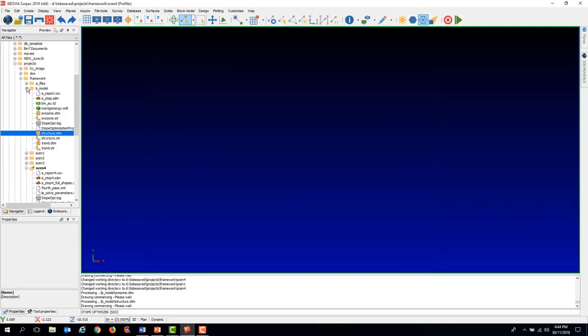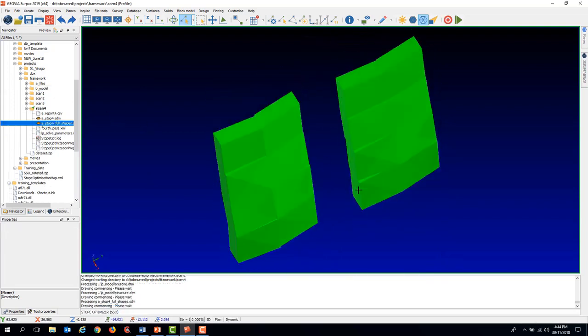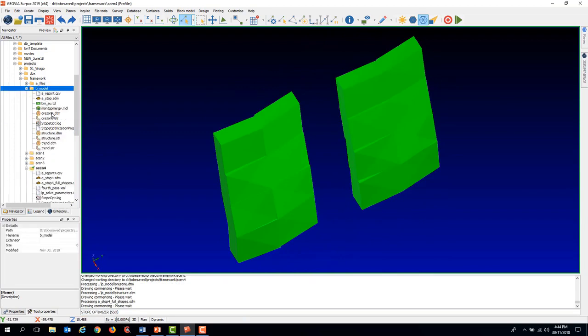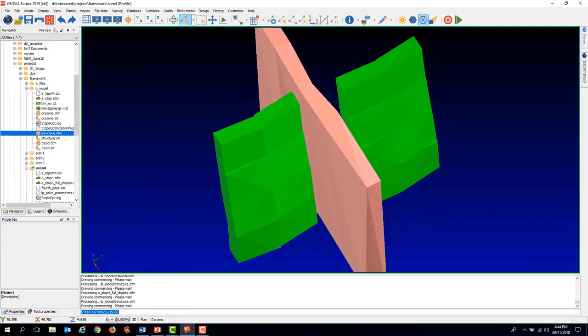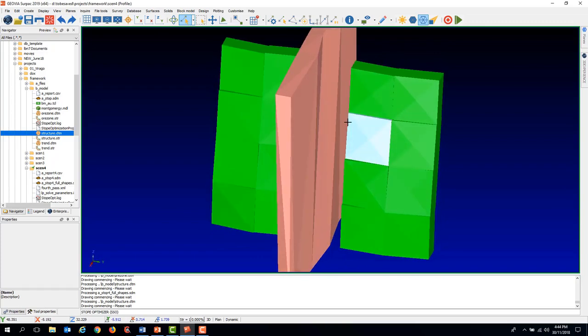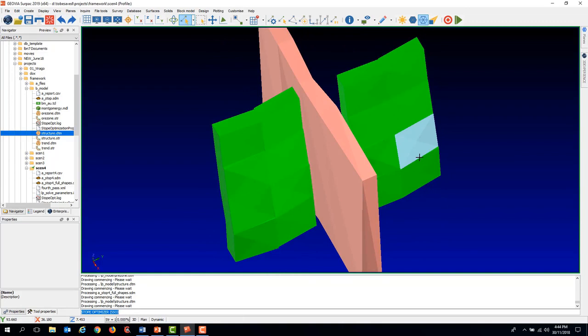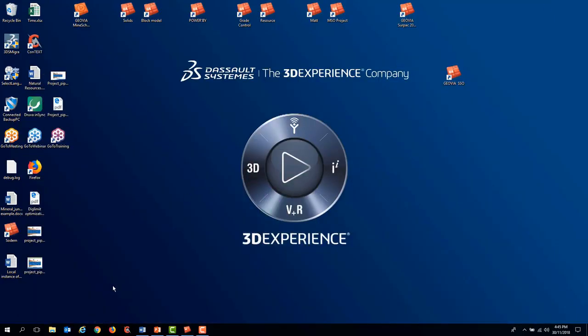So if we go and have a look at the shape that's been generated, we can see here, and if I just drag and drop the structure back in again, just so we can see what that looks like, we can see that the optimizer has run. I've just done full shapes. If I'd allowed subshapes, I would certainly generate additional stopes closer to that no-go zone, but I elected not to in this case. So that's just showing some of the examples of how to vary some of the inputs into the optimizer. So we'll leave Sepik now, and we'll just head back to our presentation.